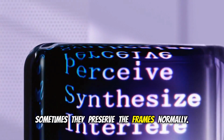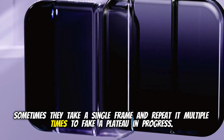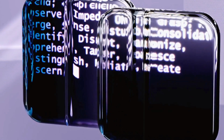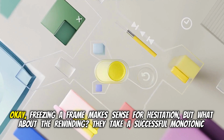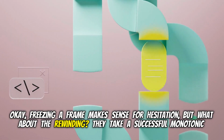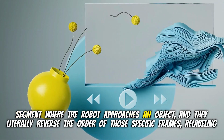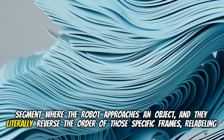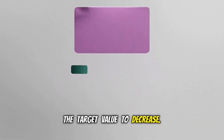They take an expert trajectory window and artificially manipulate the frames. Sometimes they preserve the frames normally. Sometimes they take a single frame and repeat it multiple times to fake a plateau in progress. This simulates a robot hesitating or stalling. Okay, freezing a frame makes sense for hesitation, but what about the rewinding? They take a successful monotonic segment where the robot approaches an object, and they literally reverse the order of those specific frames, relabeling the target value to decrease.